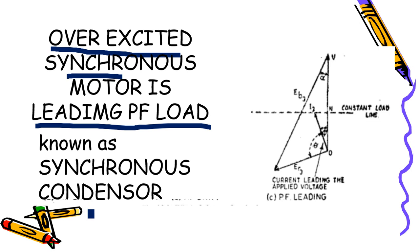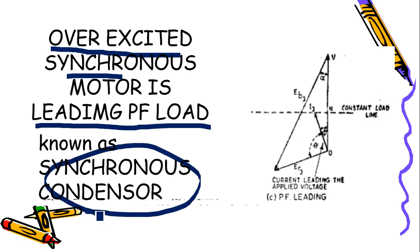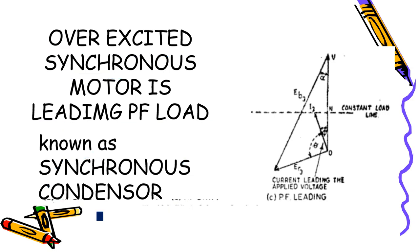This condition will be known as what? Synchronous condenser. Why? A condenser, or capacitor, takes a leading current. Here the synchronous motor is becoming a leading power factor load, and it is known as a synchronous condenser.